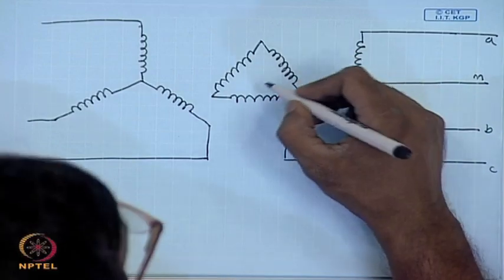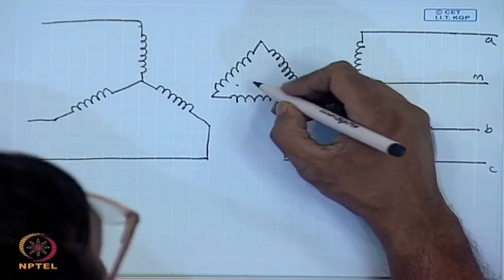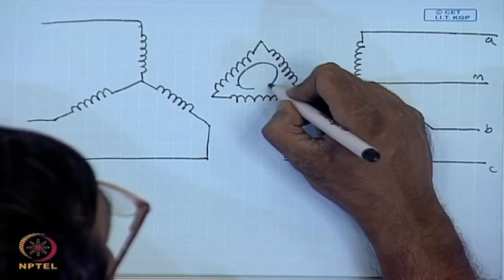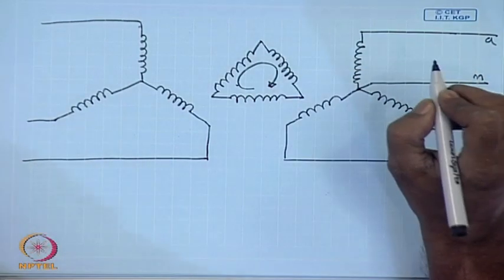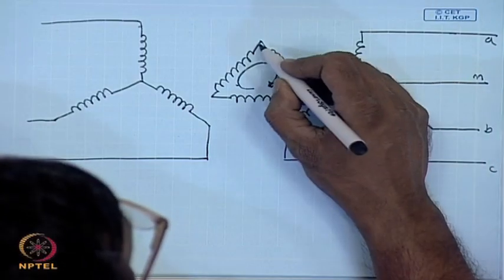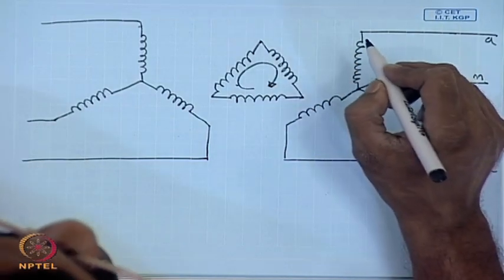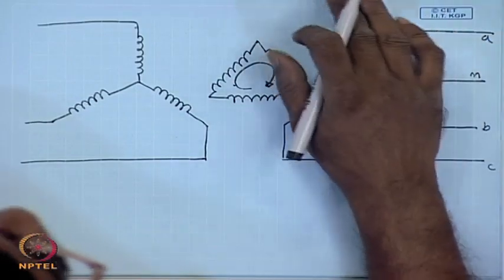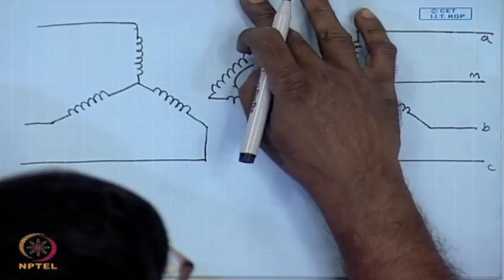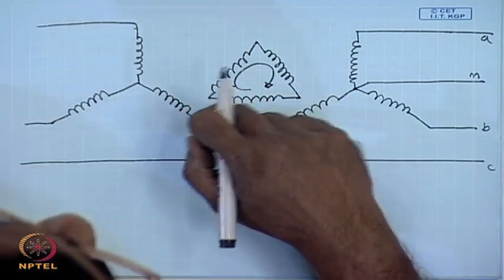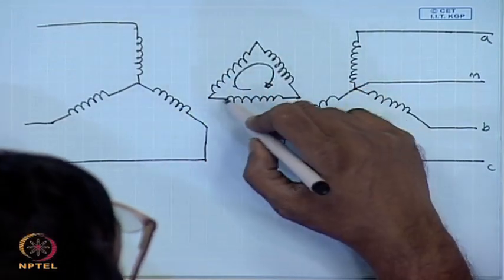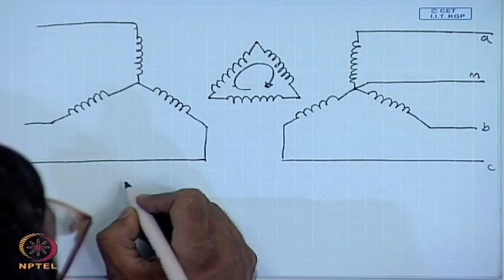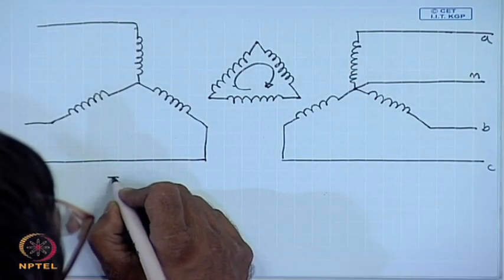When we provide a delta connected winding like this, then the co-phasor current, the zero sequence and the triplen harmonic currents can circulate within the delta winding, thereby cancelling the co-phasor MMF completely. In many cases, such a winding is provided, and those transformers are called the 3 winding transformer.